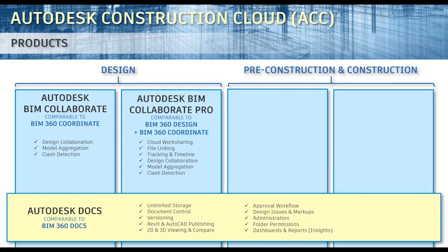And as a precursor to next week, and just so that you can get the full picture of what the ACC offers today, I want to give a brief overview of the two products that are focused on pre-construction and construction within the ACC as well. So the first is Autodesk Takeoff. This is a new product that's being offered now with the rollout of the ACC. This product mainly focuses on estimators, as it has some pretty robust quantification tools that can take your models and files, break them down into manageable parts or groups in order to do detailed quantity takeoffs that can then be exported into other cost estimating software.